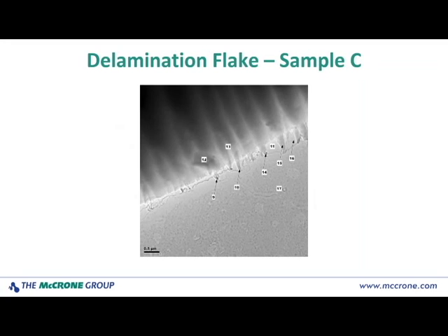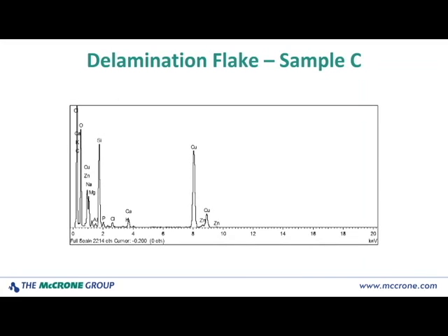And you can see that along this area there's some alternation of contrast, and this is probably just differences in thickness and fracturing of the glass, but all of the numbered areas indicate places where I was able to get EDS spectra, just to see if the differences in contrast or very small dark contrast features might reflect a difference in elemental composition. But in this case, everything looked very uniform and again looked very typical of a glass material.